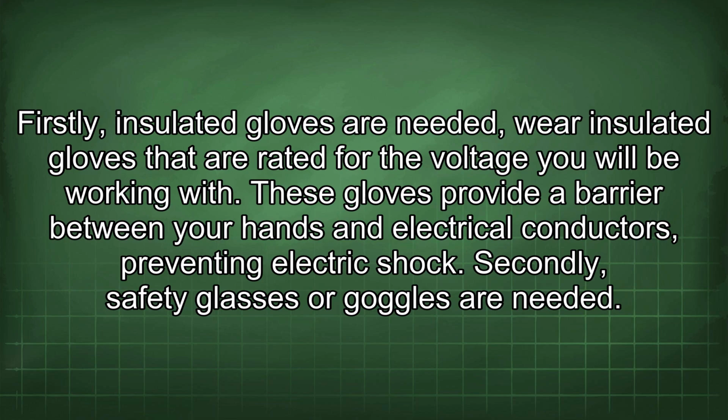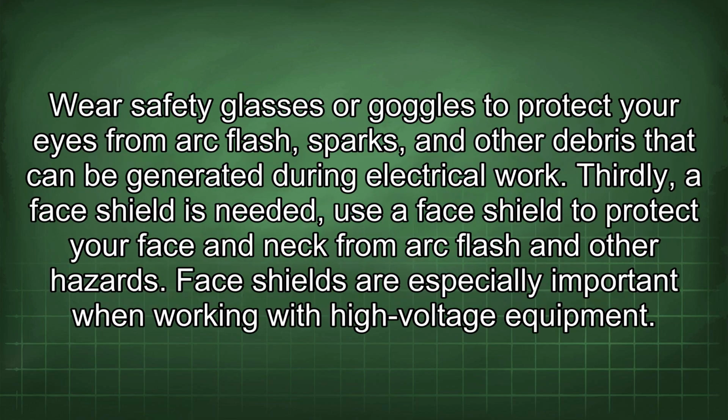Secondly, safety glasses or goggles are needed. Wear safety glasses or goggles to protect your eyes from arc flash, sparks, and other debris that can be generated during electrical work. Thirdly, a face shield is needed. Use a face shield to protect your face and neck from arc flash and other hazards. Face shields are especially important when working with high voltage equipment.